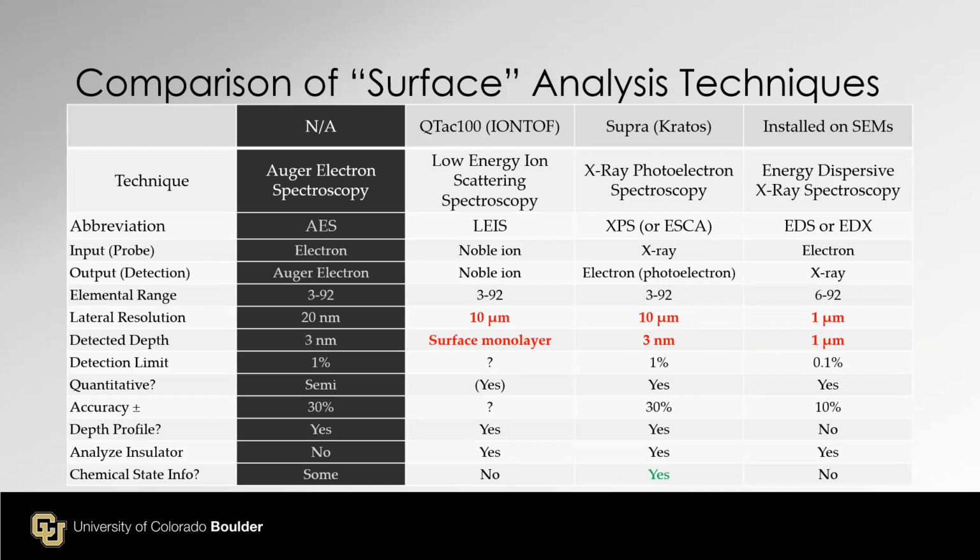Depth profiling, no, because EDS is typically mounted on an SEM chamber, and SEM chambers do not have an argon sputter gun. 99% of the time it is possible, but typically no. Analyzing insulator, yes, we can coat the insulator surface with a thin conductive layer.